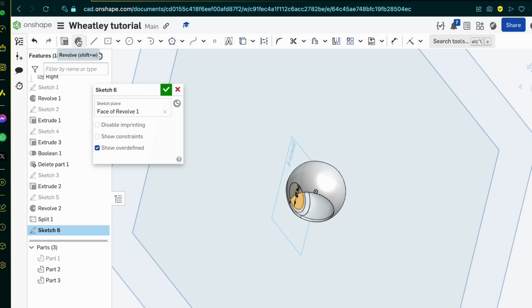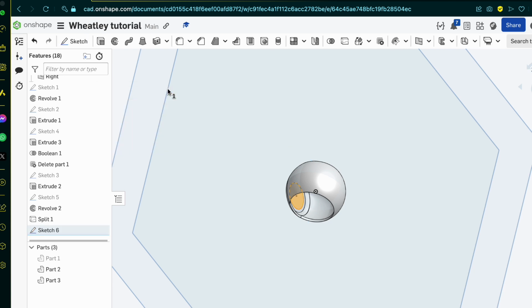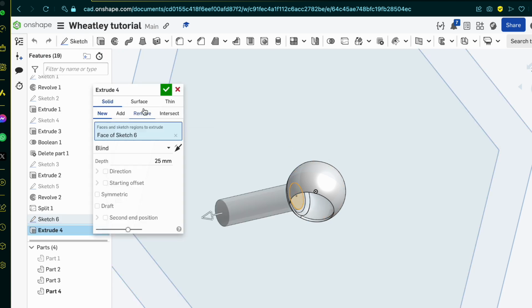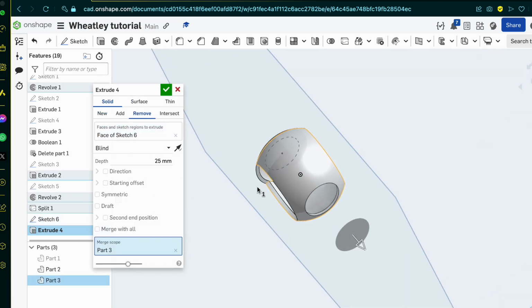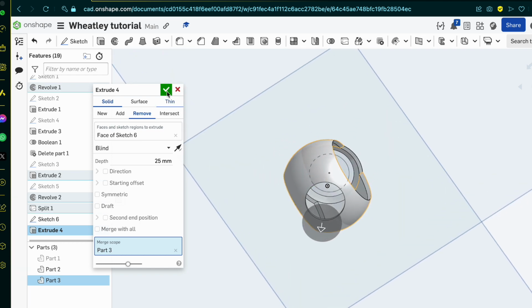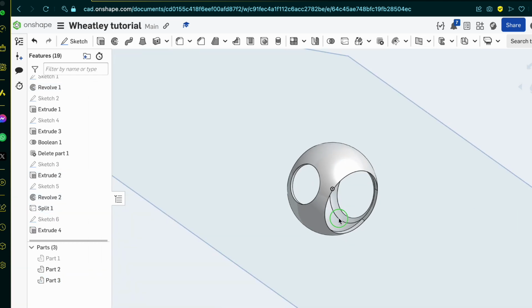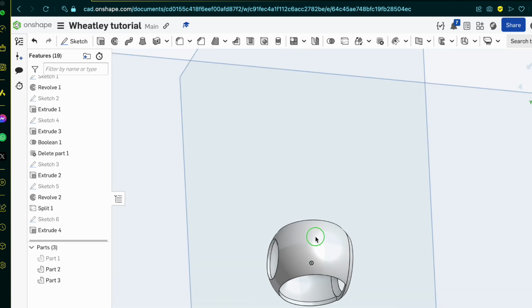So I think so far I've only used them directly from the sketch. So tick there. We've still got that highlighted. Now extrude and remove. You see, it automatically realizes that removing flips it, and the only thing it can pass through is this here at the back. Now that looks alright.